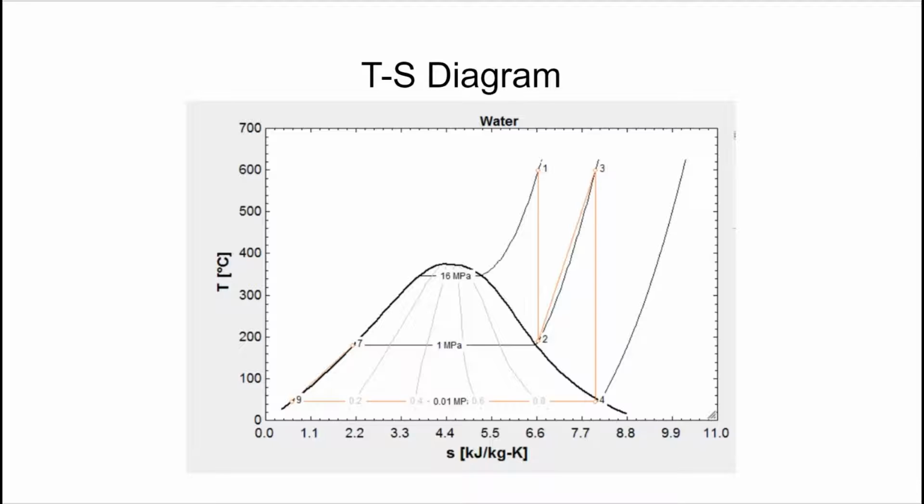So our next slide is our TS diagram, and as you can see, it's labeled with points and shows which way it'll be going in orange, and our pressure states are also on there. The TS diagram shows the location of each state and the flow in relation to the vapor dome. Our TS diagram matches what a TS diagram for a Rankine cycle with 2 pumps and a water feed heater should look like. It shows the different states' pressures, temperatures, and their enthalpies.